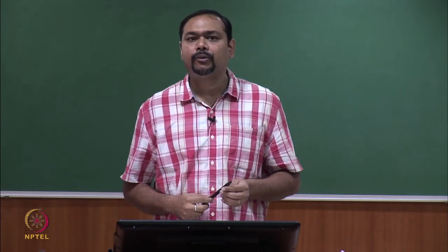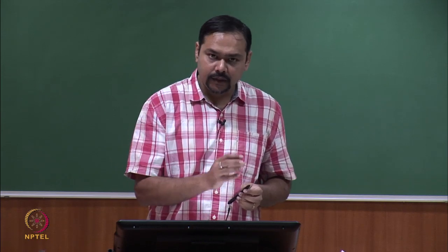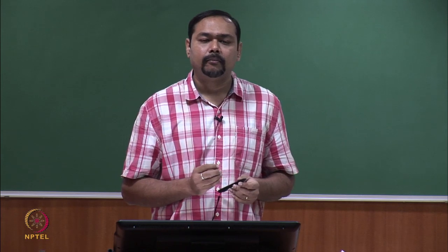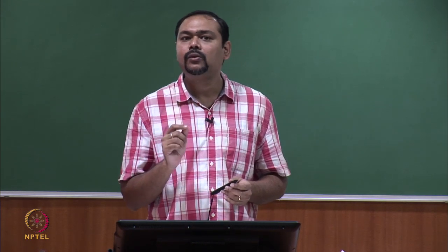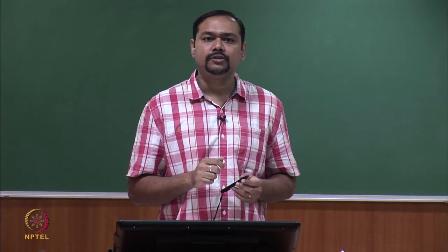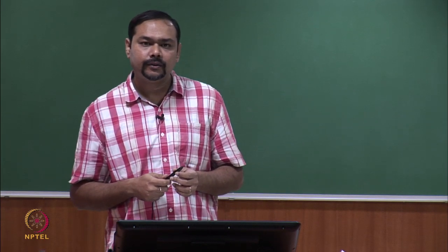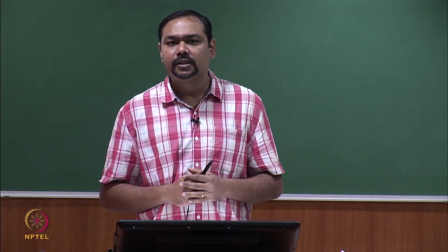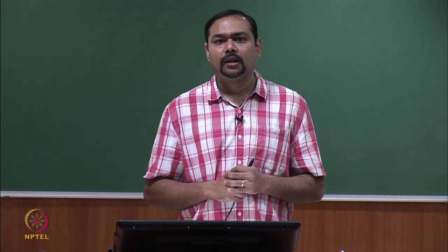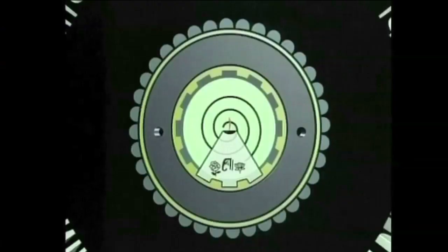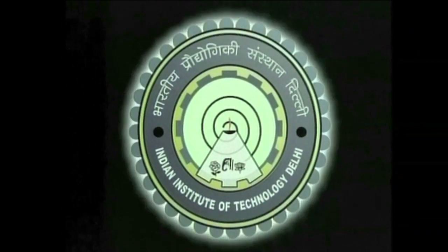We are not going to talk about it, but this discussion tells you that there are many possibilities by using this degree of freedom of point O, because point O is the converter's neutral point and it is completely floating. It gives you a degree of freedom. So, we will conclude the discussion on the cascaded H-bridge now here.